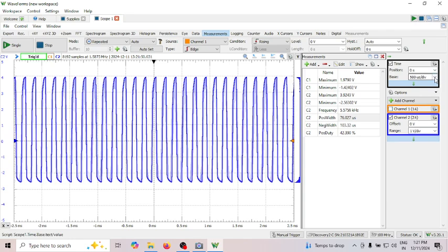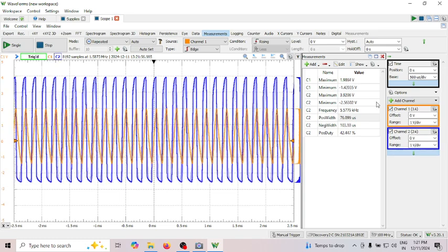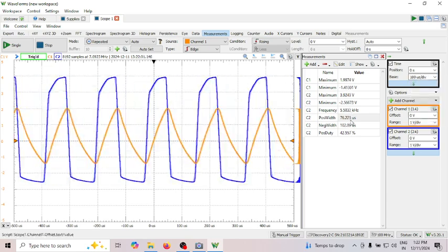Let me just turn on this. This is my capacitor charging, discharging. Of course, we have these limitations, so you cannot increase the frequency too much. It's again because of your slew rate issues. So you cannot get very high frequencies using this op amp, which is 741.